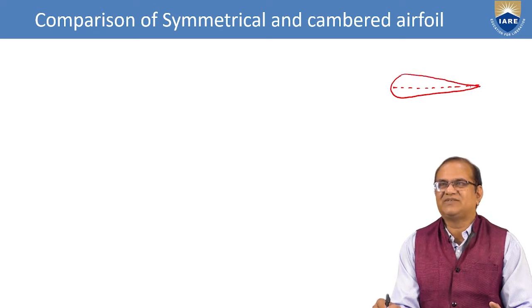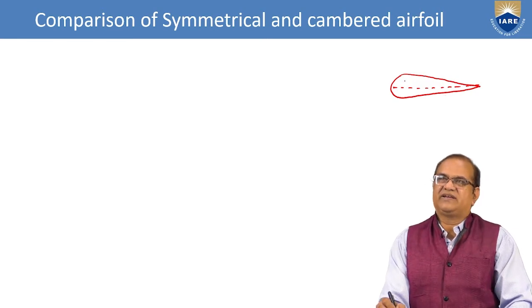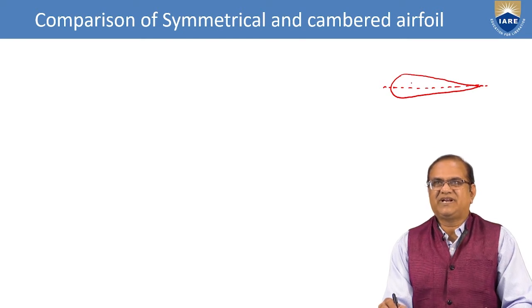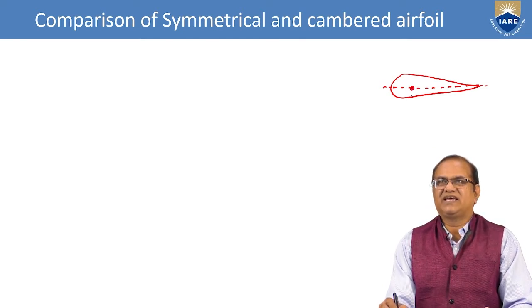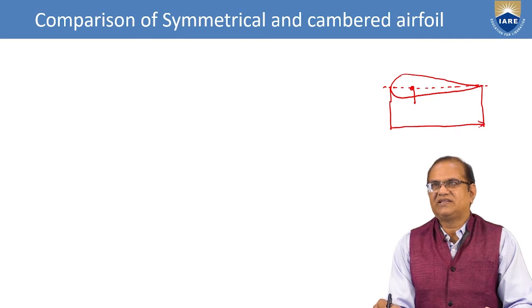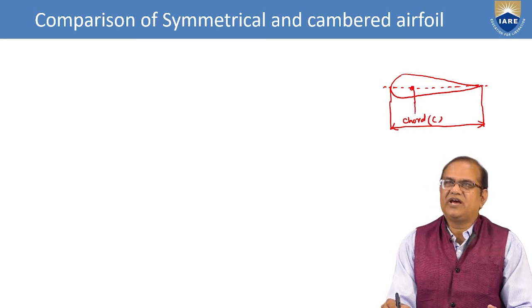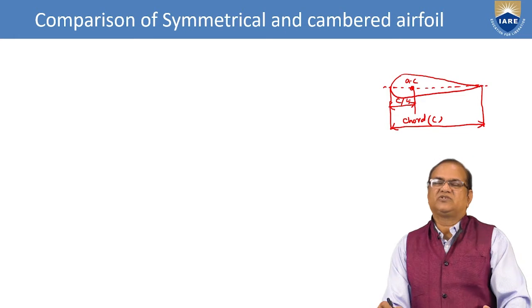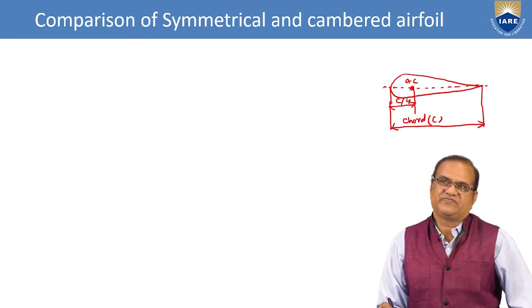Very important in the symmetrical airfoil, if this is the chord length, expressed as small c, your aerodynamic center AC will be at c by 4. So that is the specialty of the symmetrical airfoil.